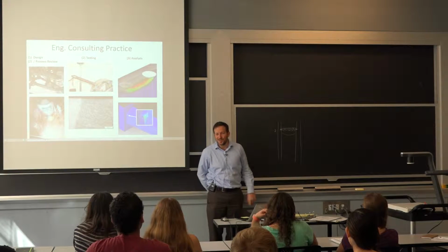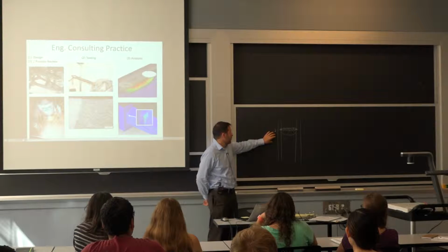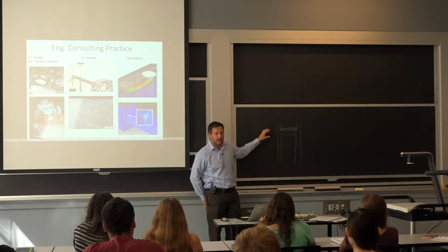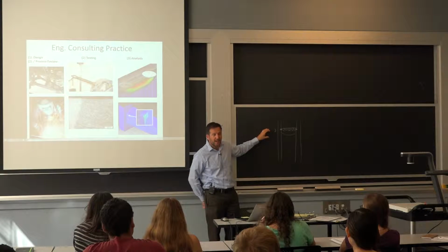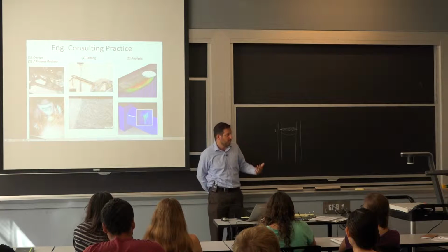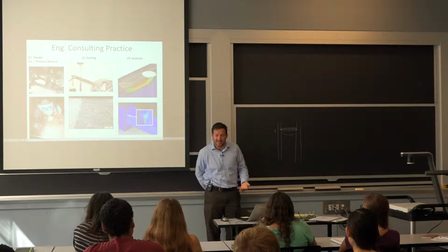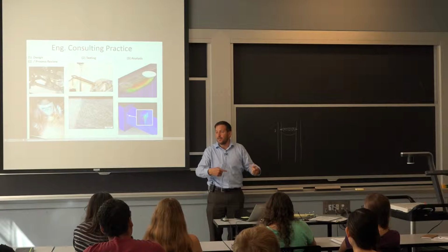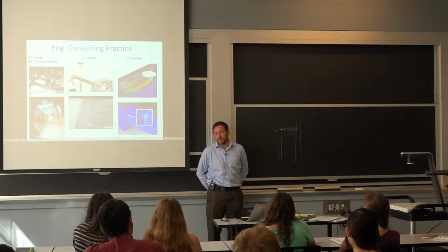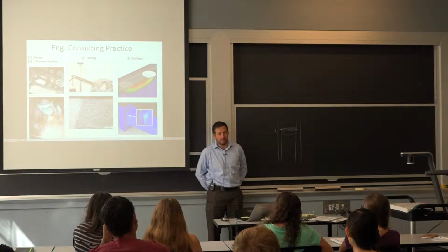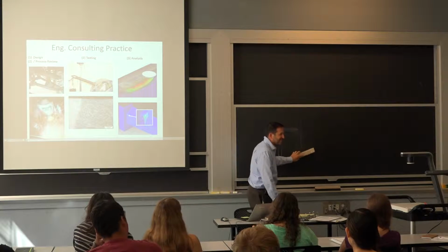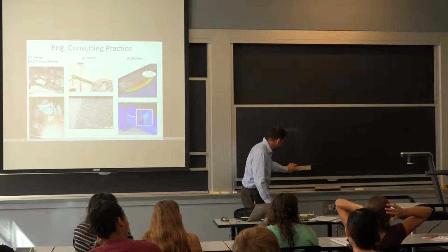So in terms of the failure analysis, perhaps the point to remember here is a lot of times it's very nice, you've done a lot of analysis, but does it fit with what really happened? So it's always good to go back to see what you can learn. I mean, we can't go back into the building, there weren't any sensors, but just seeing the buckling, the pulling in from the outside of the building was a confirmation that this theory was solid. All right, so that's that for this one. Connections failed, and that's why it collapsed.